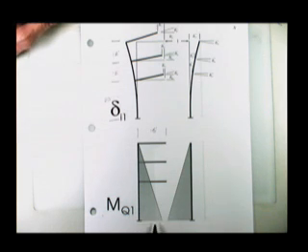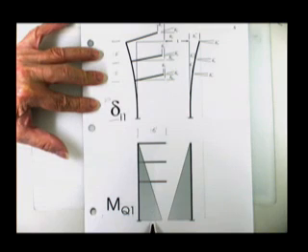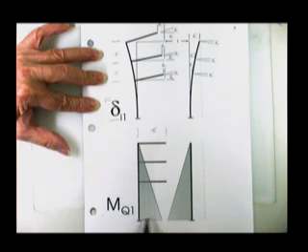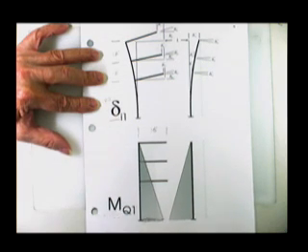It'll be the sum of, let's see, what's the length of that one? It's 20, 12, 12. That's 44 tall. 44 tall times 18 divided by 2. Well, now wait now. You're trying to give me an area here. You're probably getting ready to do some kind of volume integral stuff. It's a little too soon for that. I'm still trying to get the moment diagram so I can do volume integrals in a minute. I want to know how big is this number right here. It's a moment.